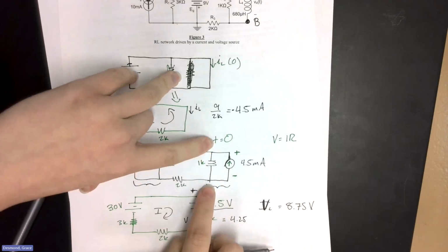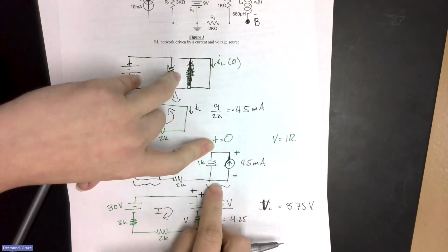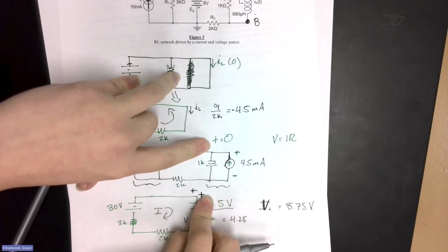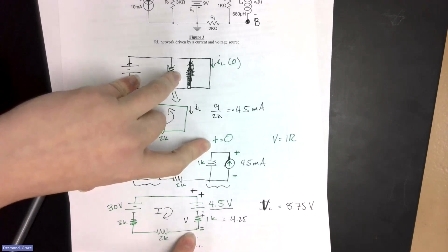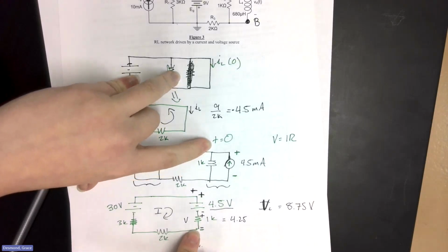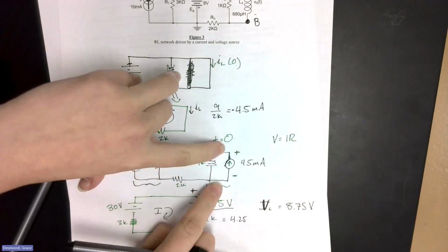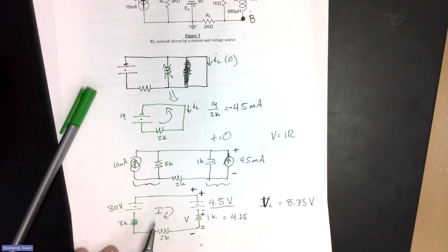And on this also, the current gets divided out, but 2 things in parallel are always going to have the same voltage, right? So that's why we can just say, okay, the voltage between the top and the bottom is the same as the voltage across the resistor and across the current source. So we combined them. We found the current, which I didn't write down.